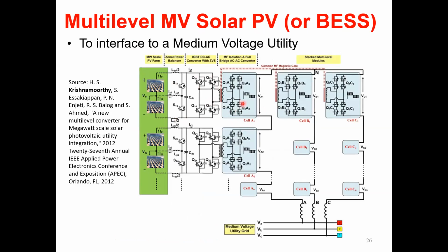You can see that there is an AC converter on the right side. Here, we assumed that eventually we wanted to give a provision where some of these panels can be replaced by batteries. In that case, we needed bidirectional power flow. That's why we use this AC converter. But otherwise, we can simply use a diode and an H bridge, as we discussed before.